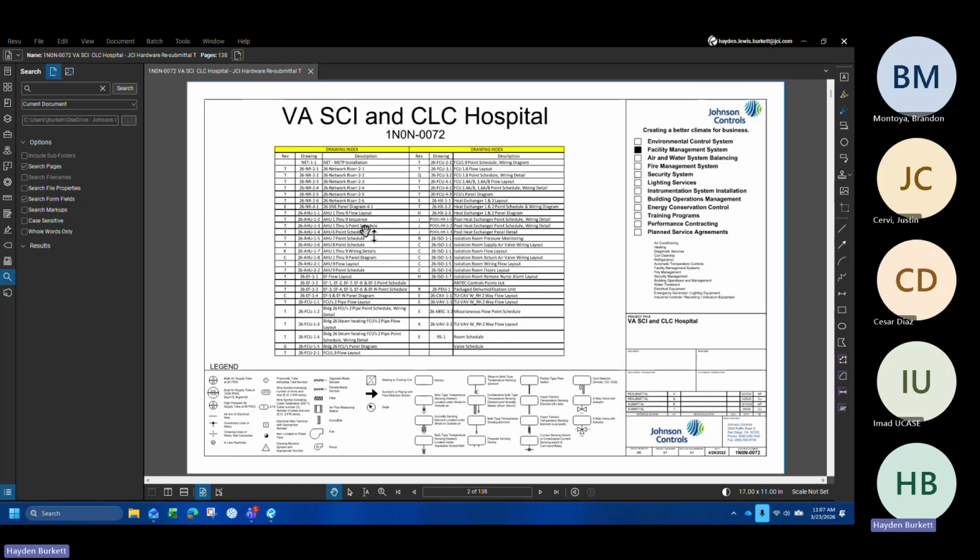We also have a couple of quote unquote exception AHUs. These are ones that have a slightly different points list, and this is due to equipment being provided that is different than the standard. Something to note would be that the outside air temperature lives on air handler 7. So that's why it has its own particular point schedule. It's because the points are different.